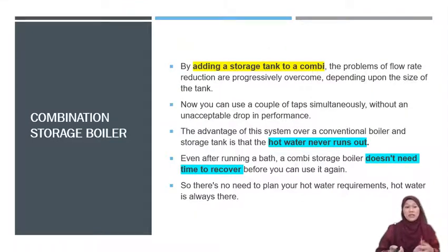Alright, there's another one. Since the Combi boiler suits a small home, what if they have a medium home? For a medium home, the best thing is to install a Combi storage boiler. That means they use the Combi system and put the storage, or hot water cylinder, inside the system to upgrade from small home to medium home, because they don't need the large size, they need the medium.